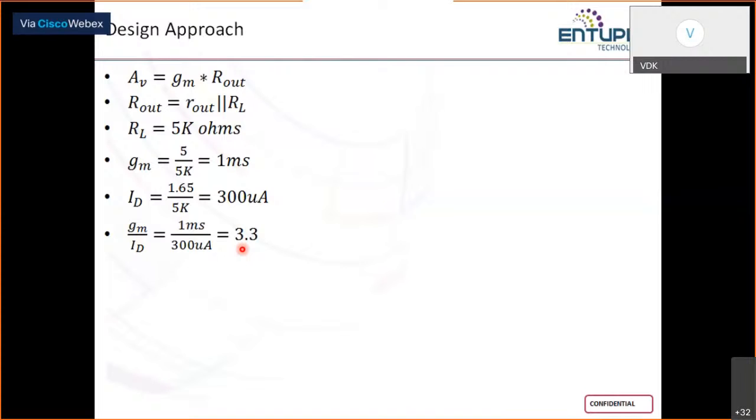Now he will illustrate with help from Naveen how we do the setup for characterizing the devices, the NMOS device in this case, for extracting curves of gm, ID, gm over ID, fT, that is the transit frequency, then Cdd, Cgg, Cgs, and Cgd. First step is that. So for this, he'll go to the tool and set up an operating point analysis for the NMOSFET. Naveen, please go ahead.